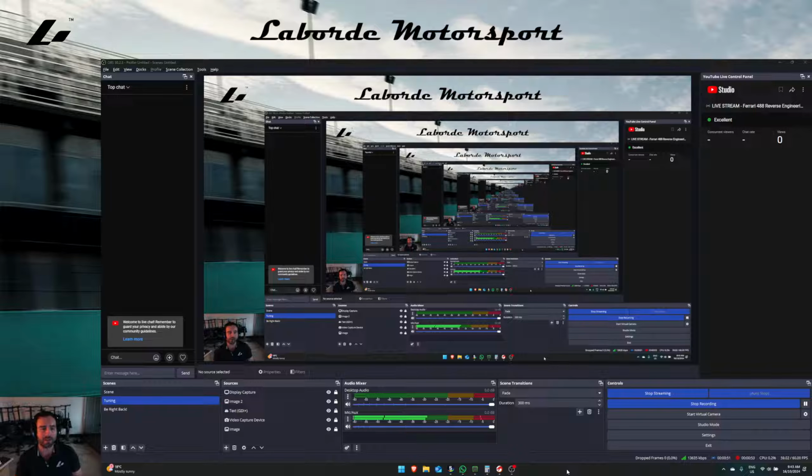ASAM standard file of the Ferrari and go through all the different measurements, calibration variables and characteristics within the file, which will allow us to link our functions, write our code and inject it where we want it, and sort of understand the structure of how that works. Another thing that we're using is WinOLS. WinOLS is a very complex and sophisticated binary editor, which is tailored towards the modification and calibration of program code for engine control units and also for transmission control units.